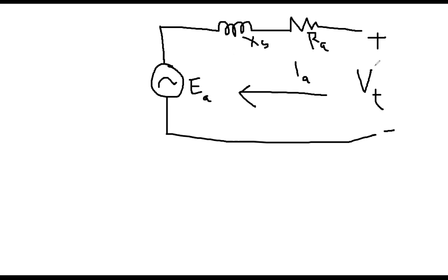But today, when I am discussing the motor, this is the first voltage: VT is applied across the terminal. Later this voltage is developed, and this is called the back voltage. I will come to that point. Easily you can understand that this is your applied voltage and this is the motor. The motor is not generating any voltage, but once the motor has started rotating, it will build up voltage on the armature or stator coils, which is the internal generated voltage. But actually you will be applying this voltage, and this is your current direction.